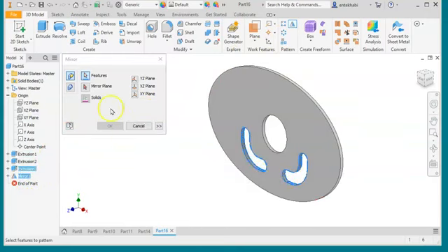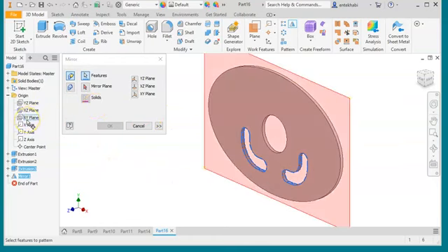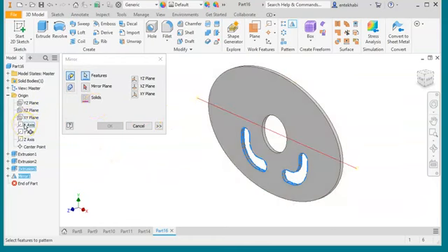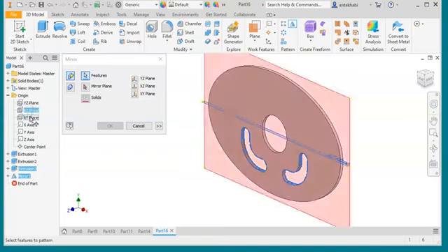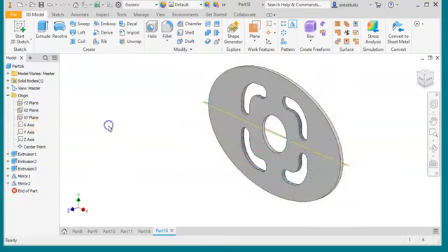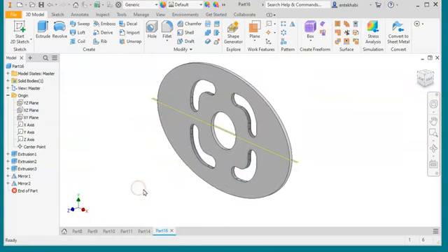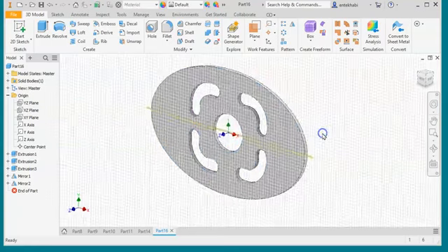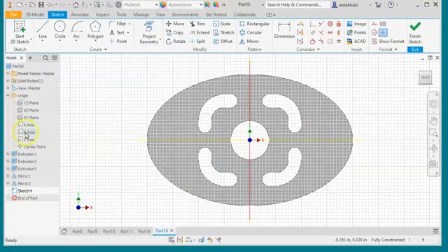And then we select the plane. In this case would be XZ plane. XZ plane. And then mirror plane, of course, is XZ plane. And then apply, OK. And that completes your drawing. Then, well, last thing we need to add, of course, is the polygon.